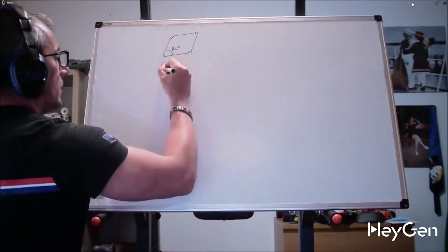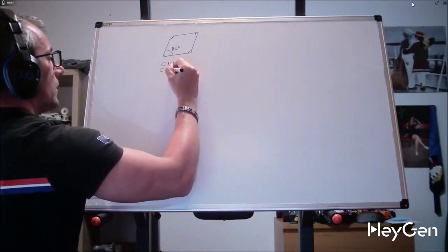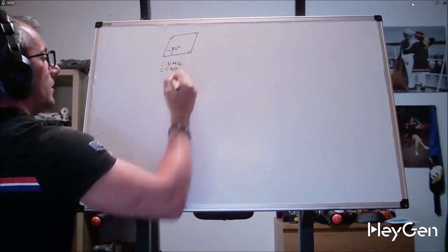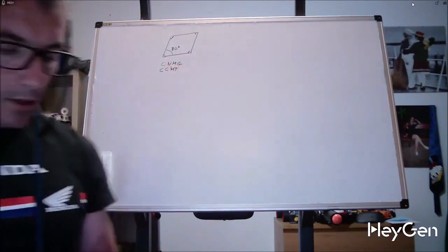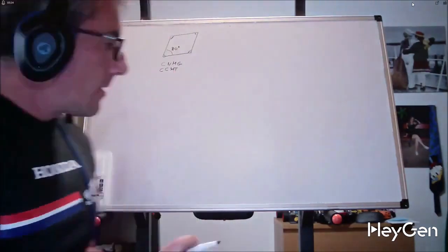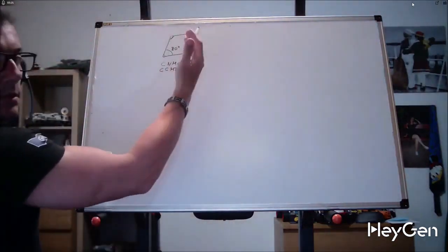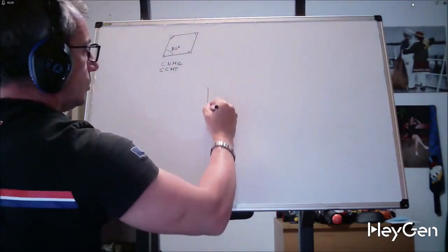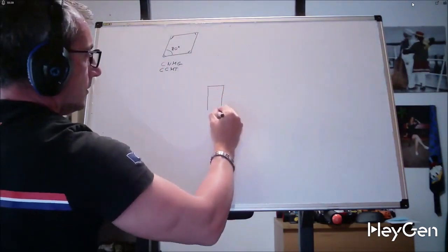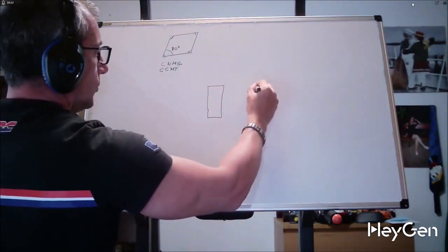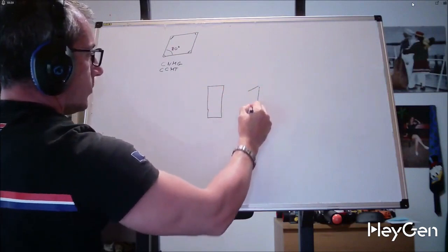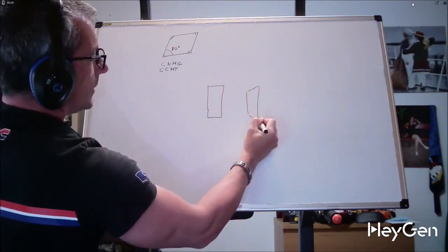CCMT inserts, if turned and viewed from the front, present two possibilities: a rectangular section or a section that we can call a bowl, where the cutting edges are. The CNMG is made like this.